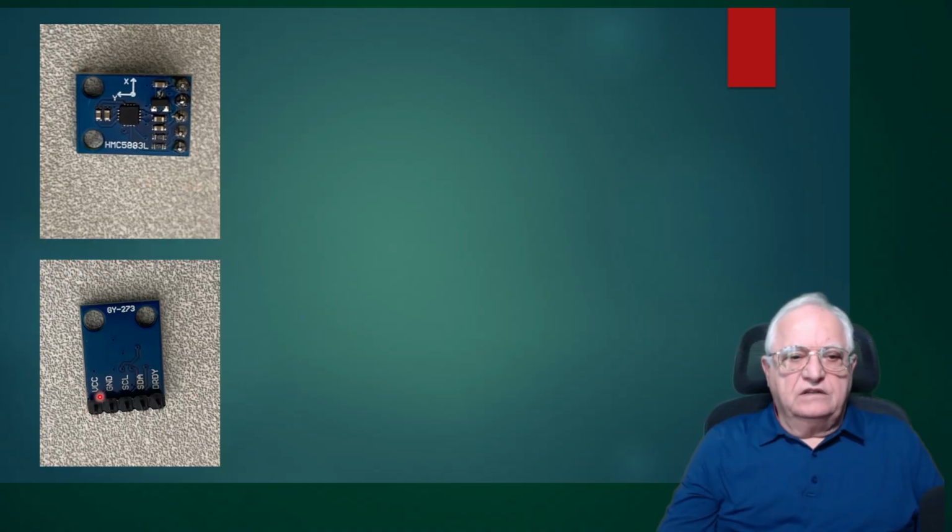The input signals are the voltage, ground, and then this is an I2C unit, communication with this unit is I2C. So we have the SCL and the SDA, and then we have an interrupt line which we don't use. Now this is the other side of the chip, and here you have the X and Y, and that gives you the axis from which it's been measured. And also the GY273 utilizes the magnetometer chip, which is this one here, which is going to be the